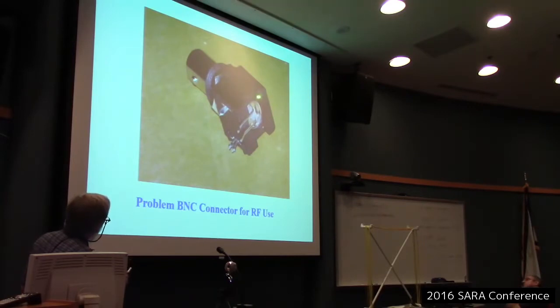So all of your ground at 400 megahertz is going back through this one little thing here, and this is up above the circuit board. If you get any currents on the coax cable that's plugged in there on the outside, the ground currents don't go to the case, they go inside the box and the ground here. So you effectively have a coupling loop to make any signals that are picked up by the ground on the coax actually couple into the inside of the box.